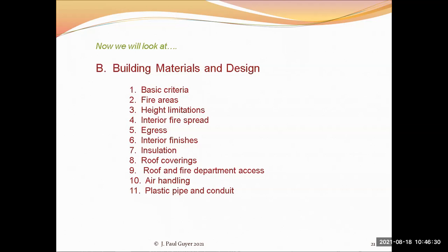So the firefighters pull up to the side of the building, connect a hose to the hydrant in the street, to the pumper truck, and then on the other side of the pump, they connect to this standpipe in the stairwell and pressurize the standpipe. And the firefighters then, because the stairwells have been constructed of a highly fire resistive nature, climb up the stairs carrying their hoses until they get to the floor where the fire is. They connect their hoses and they go in and they fight the fire.